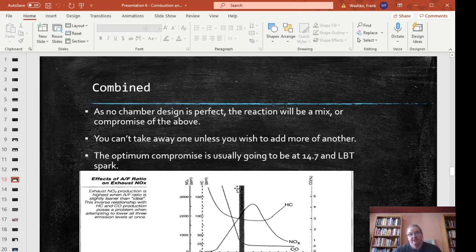The other thing is this is fuel air ratio 14.7 to 1. You remember that I talked about doing these spark sweeps where you change the spark advance. I also said that these emissions values were sensitive to spark advance. So maybe you would buy a spark advance for more performance, where there's a nonlinear curve and we could hit a high point of performance.